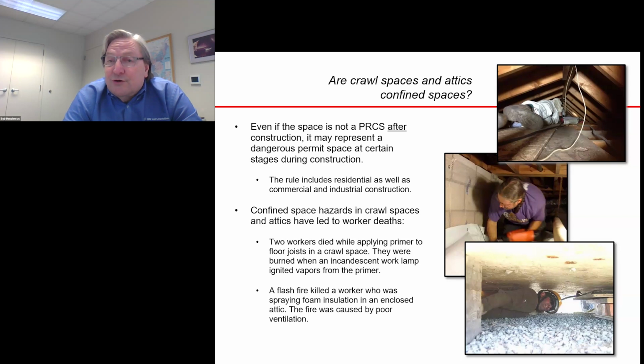Whether it's dangerous or not depends on what's going on at that moment. But if at that moment you're applying a solvent or a paint or foam that is off-gassing contaminants, maybe it is a permit space until the material has cured and until it stops emitting vapors.